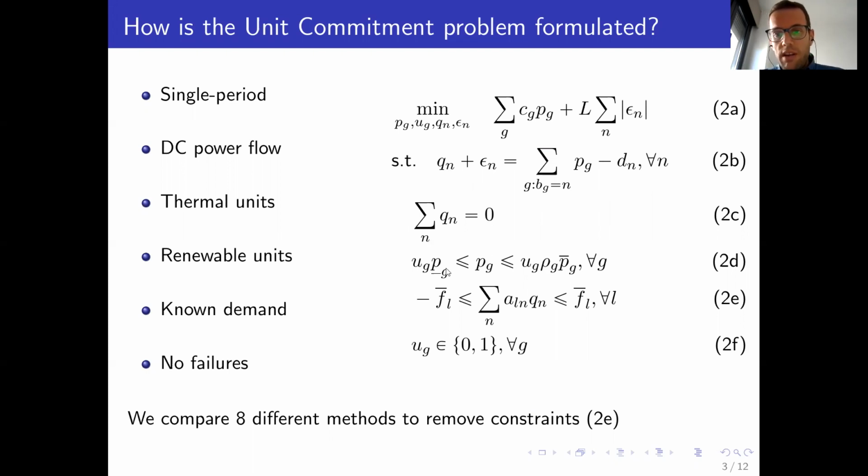This is the technical limit for the units, this is the capacity limit of the transmission constraints, and this is the binary variable declarations. The transmission constraints are very complicated because they have to be formulated with full matrices. So in an ideal world, you would like to remove as many transmission constraints as possible.